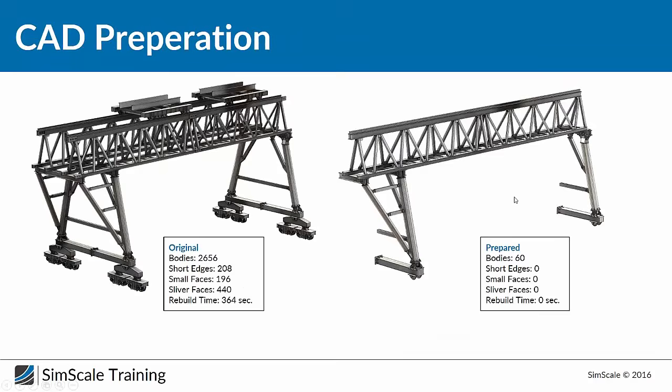When we talk about meshing, it's very important to understand that meshing is not only about creating a mesh, but it starts much earlier. Basically, meshing starts in your CAD system. Just imagine you want to simulate an assembly like this. If you take a look at the productive CAD files used by designers and engineers, you will find a very complex assembly made of several thousand bodies, having a lot of short edges and small faces, which is very hard to handle and also to mesh.